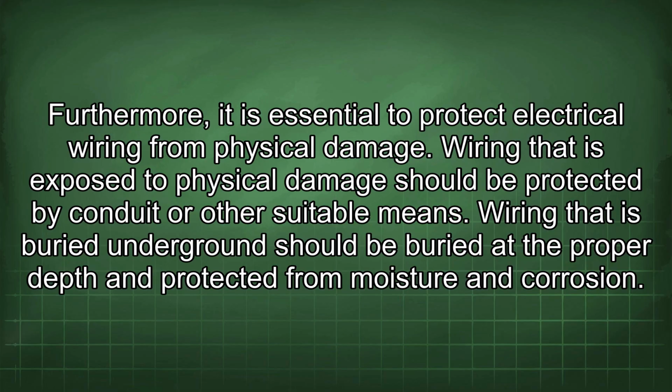Furthermore, it is essential to protect electrical wiring from physical damage. Wiring that is exposed to physical damage should be protected by conduit or other suitable means. Wiring that is buried underground should be buried at the proper depth and protected from moisture and corrosion.